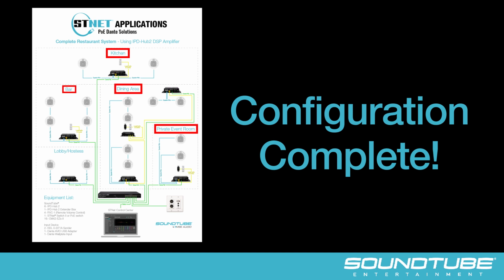The level of our paging audio in any given zone will be unaffected by adjustment of the RVC in that given zone. We also have two local audio input devices within this system, one in the private event room and one in the dining area, which sends audio to both of the IPD-Hub 2 amplifiers in the dining area. These two input devices are both Bluetooth-enabled wall plates, which will allow users to connect directly to them with their own source devices and pass audio directly to the IPD-Hub 2 that those devices are connected to.